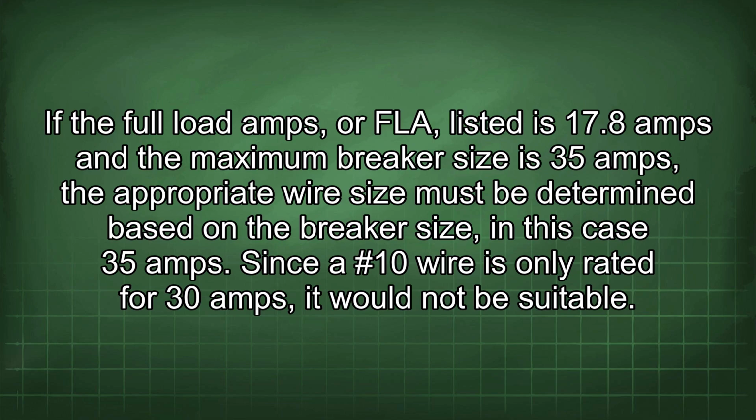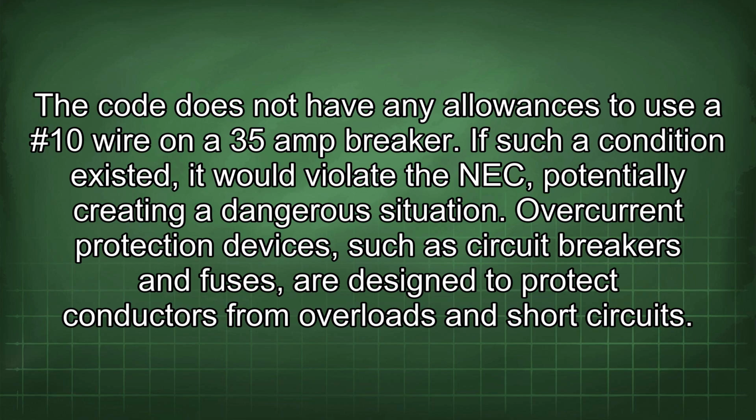Since a #10 wire is only rated for 30 amps, it would not be suitable. The code does not have any allowances to use a #10 wire on a 35 amp breaker. If such a condition existed, it would violate the NEC, potentially creating a dangerous situation.